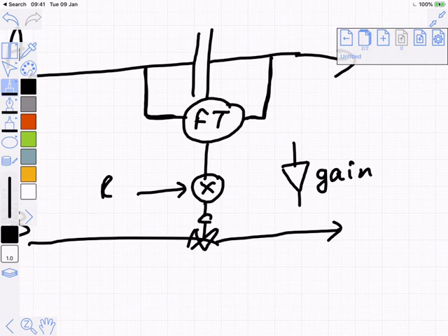What that represents is physical taps, in other words, holes upstream and downstream from the orifice plate, which are connected directly to the flow and therefore have a pressure drop over them. And this thing that I've labeled FT over here will typically actually be a differential pressure sensor.